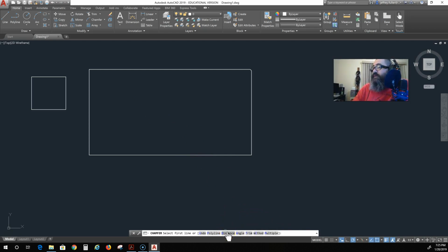We'll use distance and angle, so we'll say type D, and we'll just say 1 unit. Okay. Second distance, we'll say 2 units. Okay, so select the first line that I want to be 1 unit chamfered, and the second line for 2 unit chamfered.